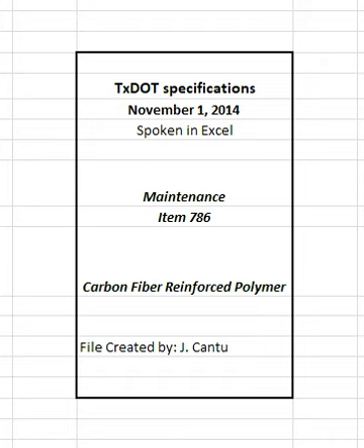4 Measurement. This item will be measured by the square foot of concrete area covered with CFRP system. This is a plan's quantity measurement item. The quantity to be paid is the quantity shown in the proposal, unless modified by Article 9.2, Plan's quantity measurement. Additional measurements or calculations will be made if adjustments of quantities are required.